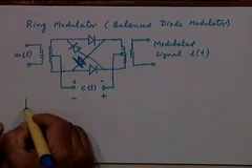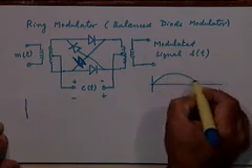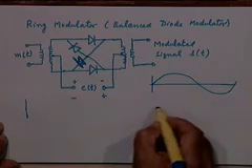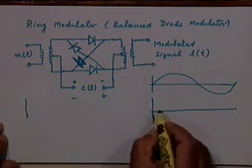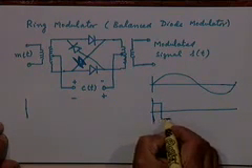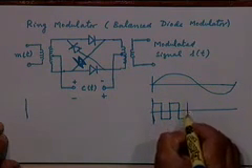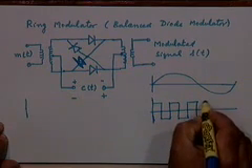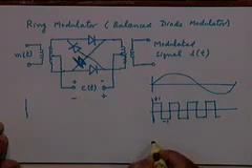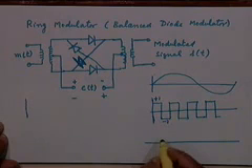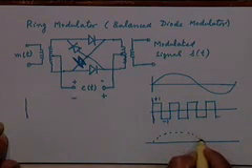So if you were to plot these waveforms, basically what we are saying is something like this. Maybe this is a better place to plot. Assume this is your modulating waveform, and to show the switching action, basically what we are saying is we are multiplying this waveform with these positive and negative pulses, or this square waveform which goes between +1 and -1, and the output would be a waveform like that.